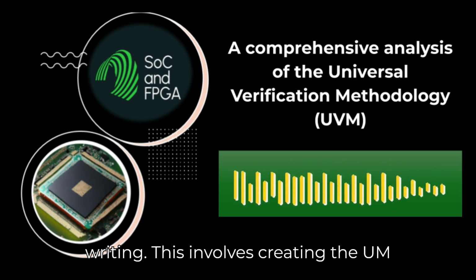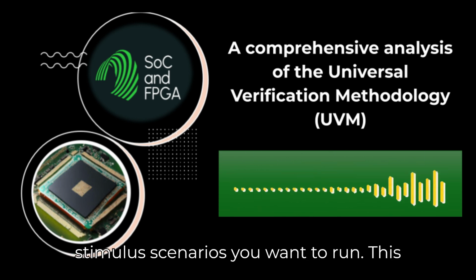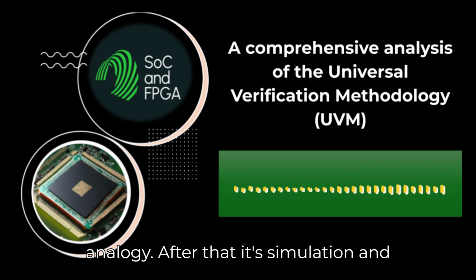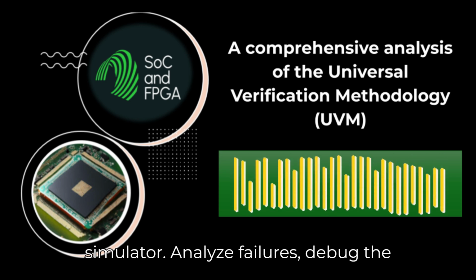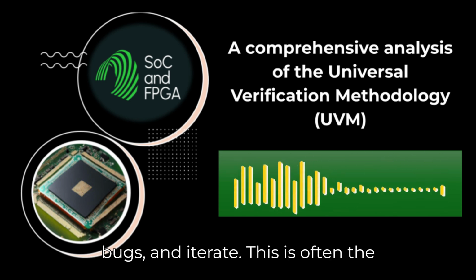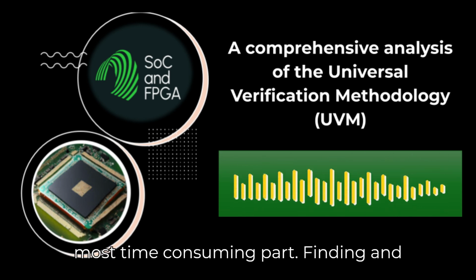This involves creating the UVM sequence classes that define the specific stimulus scenarios you want to run. This is where you encode the actual test intent. Designing the experiments. Good analogy. After that, it's simulation and debug. You run your tests on the simulator, analyze failures, debug the DUT or the test bench, fix bugs, and iterate. This is often the most time-consuming part. Finding and fixing the problems.